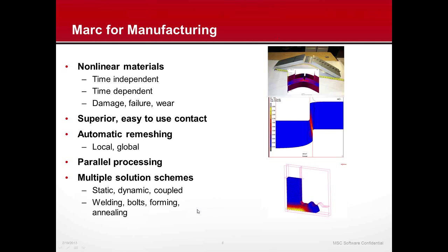And the next one is the global remeshing, and it is shown in the example here at the bottom. It is used to replace the entire existing mesh of a contact body. And there are two approaches to global remeshing. It could be either manual or automatic. And especially with the automatic one, the effort on your part is much less. Whenever certain elements exceed the distortion, and if there are some convergence problems, Marc would automatically replace with a new mesh.